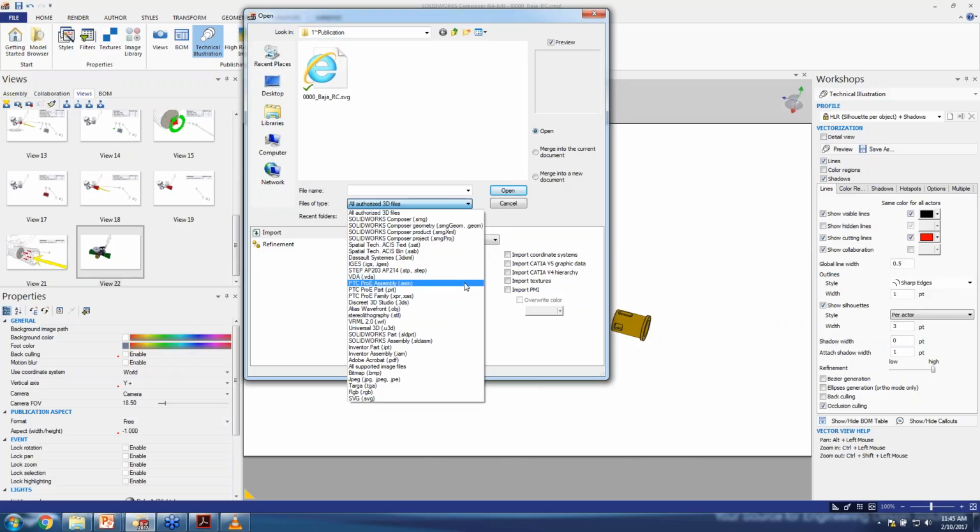And actually IGES is my preferred method that way because it keeps the assembly tree. And from what I've tested, it also keeps the associativity. I haven't fully tested that with large examples, but it seems to hold up pretty well because it jumps into that IGES file, it sees the bodies, and it compares the bodies after an update. As long as the bodies haven't changed name, which is their file type in CATIA, then the update remains. And it actually works out pretty slick. So yeah, great question, but I'll just leave this open if anybody else is looking at the different file types still.